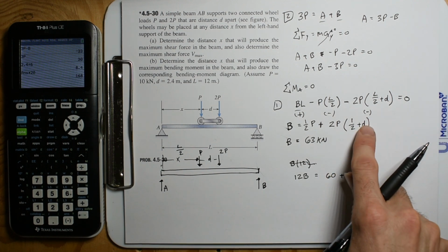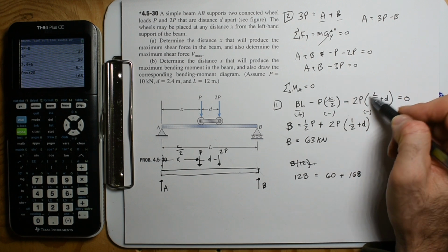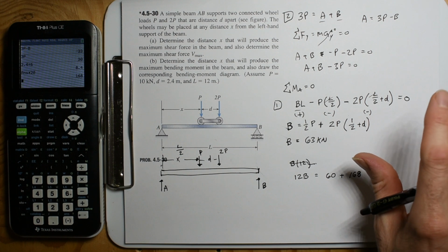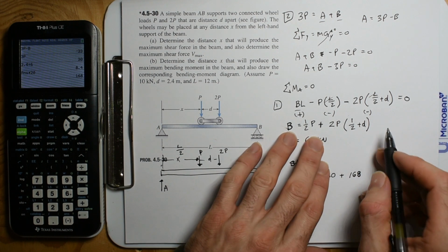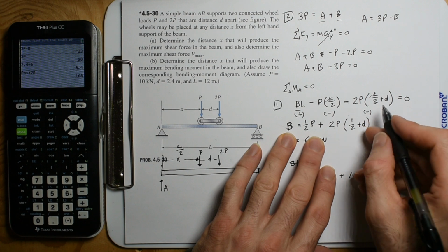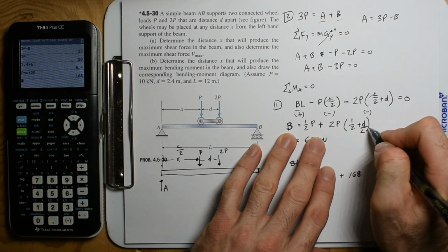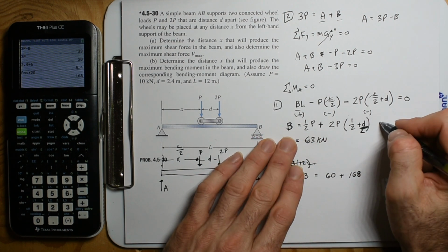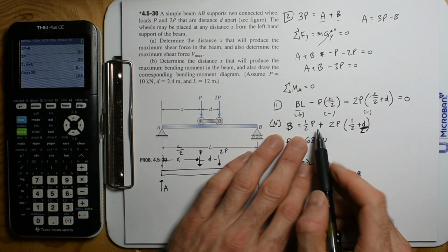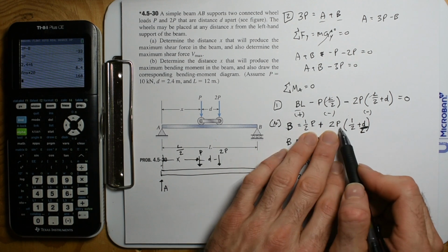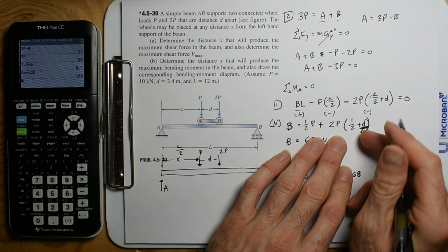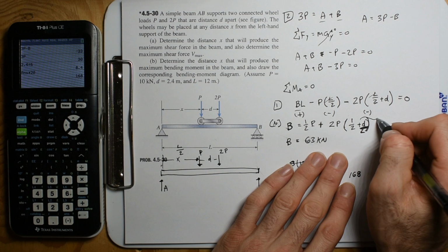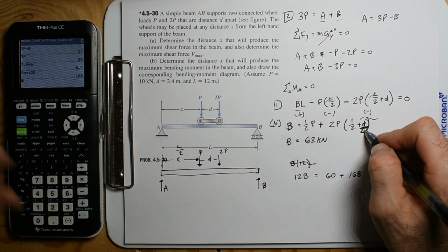Oh, you know what? Yeah, no, I can't just factor out a length because I have a length right there. So my bad on that. I had to keep that in. So if I did that, I would have D divided by L. And that makes sense because you can always check your units. If this is going to be in newtons, okay, I have a force in kilonewtons multiplied by this, so these must have dimensionless units, and since I have a distance here, I've got to divide by L.